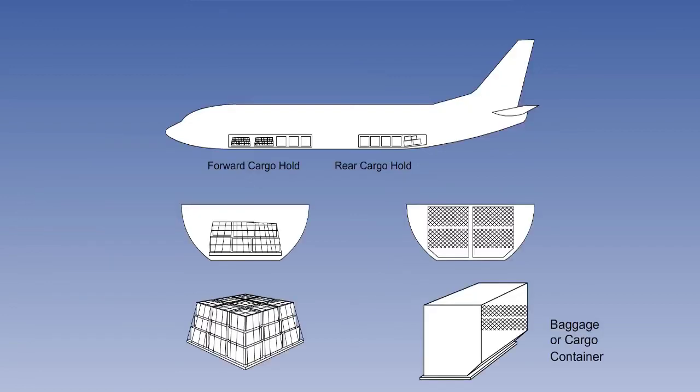During this lesson on cargo handling, we have learnt the various methods of locating cargo in the aeroplane's cargo holds, and how important it is to comply with the floor linear and area loading limits. We have learnt by calculation the acceptable way to place loads on the cargo compartment floor to avoid structural damage to floor and frames. We also know that there are a number of ways in which the cargo can be restrained in the hold to prevent movement.